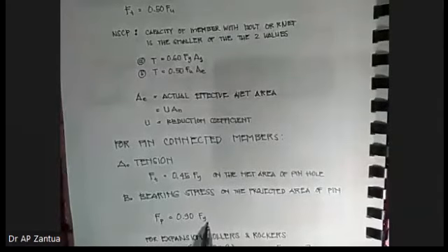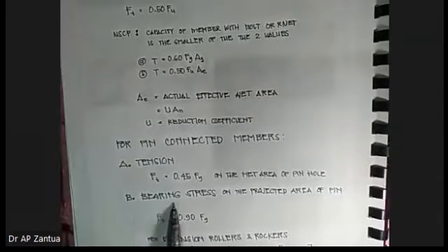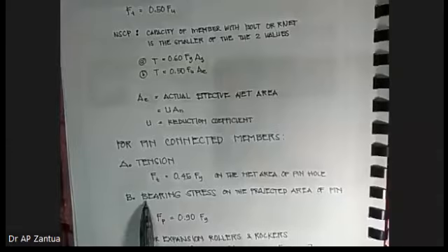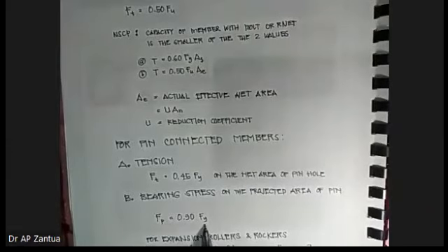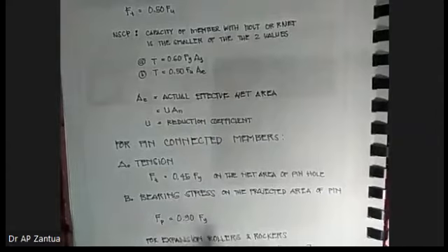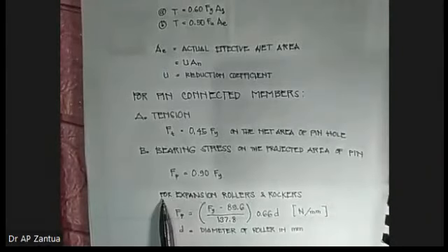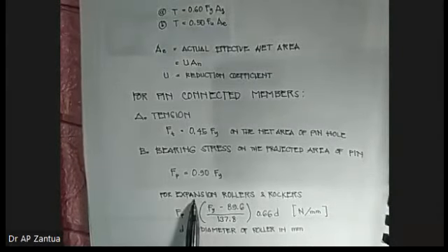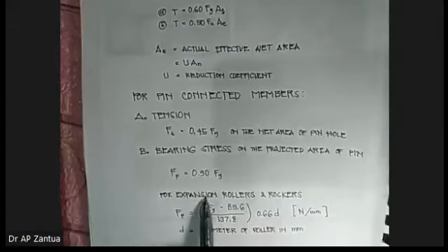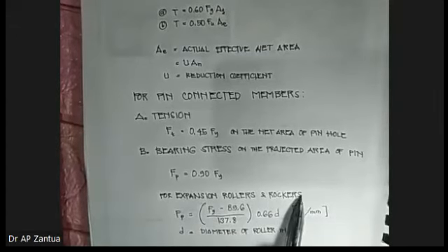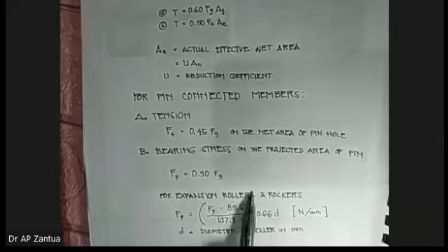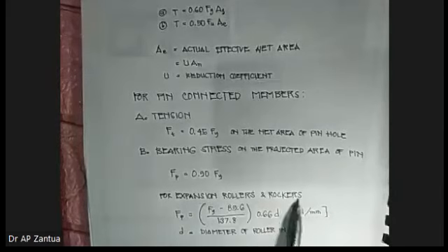So when we are going to solve bearing stress, that is 0.9 of Fy. And if you would like to know the bearing stress for expansion rollers and rockers, a roller meaning it is a circular member, a rocker.